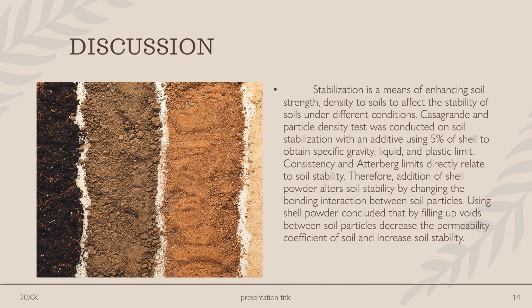Consistency and Atterberg limits directly relate to soil stability. Therefore, addition of shell powder alters soil stability by changing the bonding interaction between soil particles. Using shell powder, it is concluded that by filling up voids between soil particles, the permeability coefficient of soil decreases and soil stability increases.